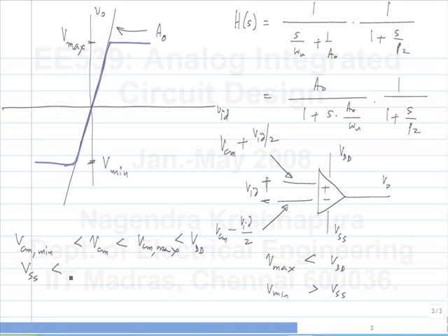So normally, if you say a classical op-amp circuit, what's the value of VDD and VSS and VCM? Plus or minus? Yeah, or not necessarily. It's plus or minus. This is some positive voltage and this is equal negative voltage with respect to ground. And what is the value of VCM? 0.